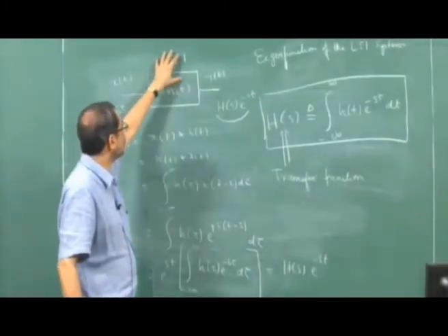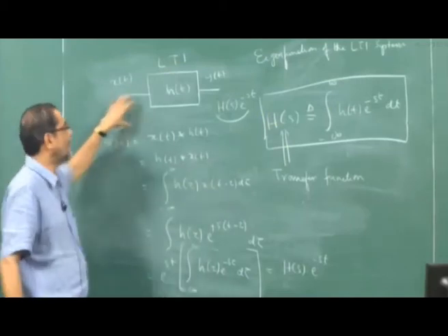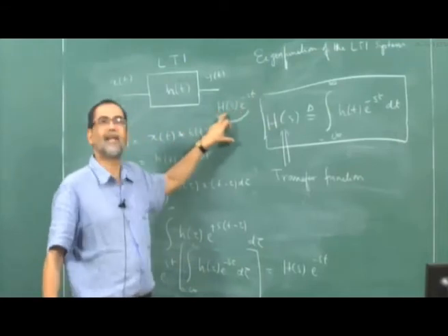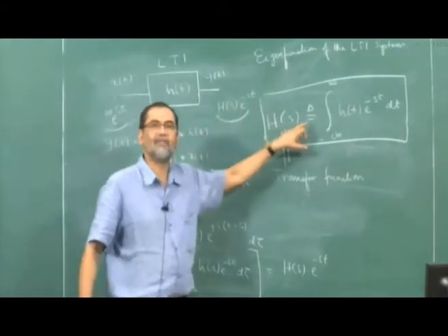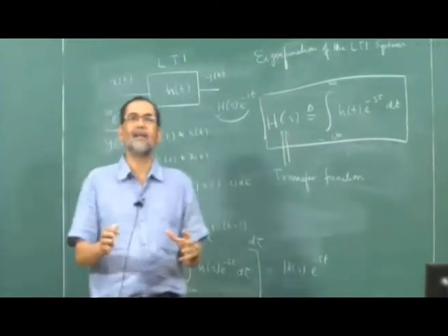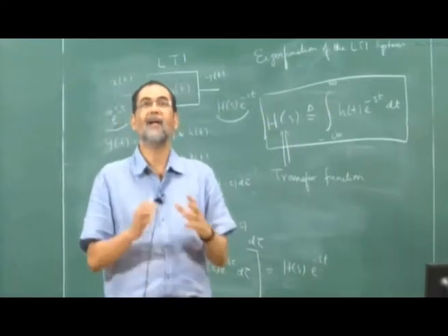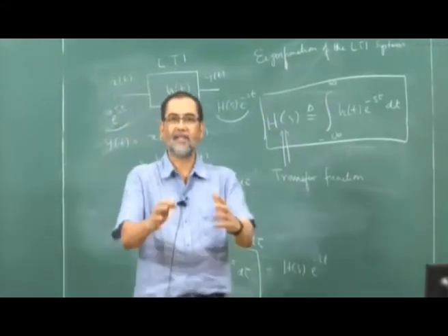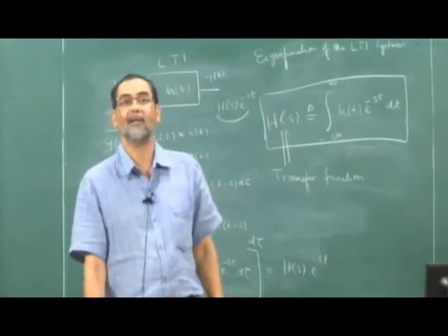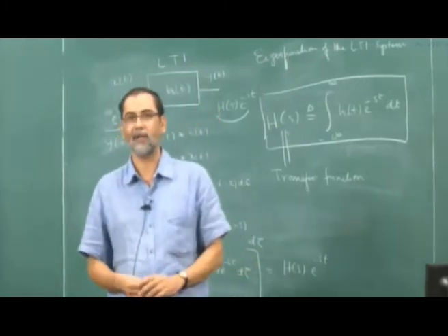An LTI system, for input e raised to minus st, gives output with the same frequency, e raised to minus st, with some scaling factor H of s, called the transfer function, defined by this integral. So this idea that linear time invariant systems preserve the frequency leads to the study of linear systems in the frequency domain. That is what I am going to do next. So that is the motivation for switching to the frequency domain.